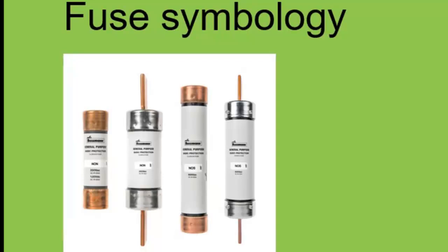How it functions is that once a certain load is carried, that fusing element will fuse over some time, due to the I squared R effect. So it is basically for the protection of the circuitry. That is why fuses are installed in the circuit, in series with your load, which means that whatever current or load is flowing through the circuitry will flow through the fuse.